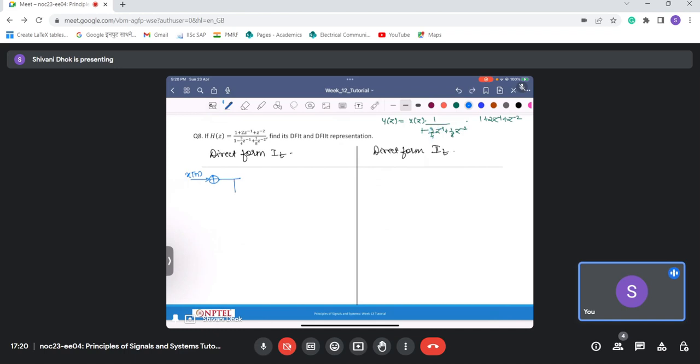First I'll scale it by a factor of 3/4, and then I'll delay it, something like this. Then I have this factor of 1/8 here, so I'll have a gain block of minus 1/8 and a delay block here.